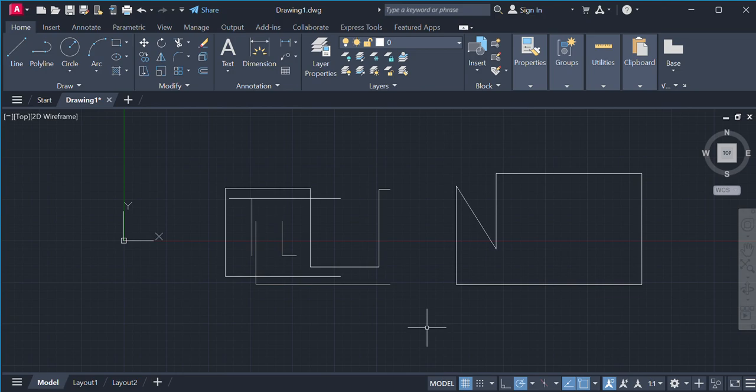So if it happens that you are drawing your floor plans or trying to draw an object, either your manholes, once we get to the hydraulics chapter, just make sure you don't use the polyline command, because once you've used the polyline command, it essentially means you cannot delete part of that work. If you want to delete, you have to delete everything.